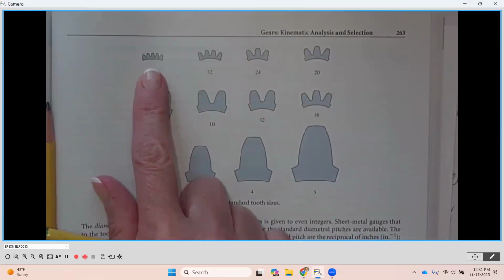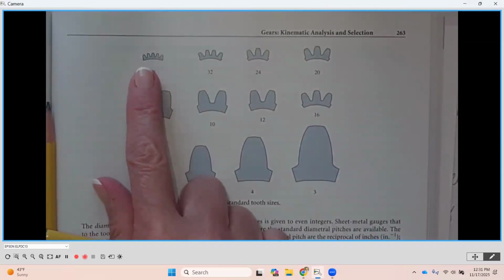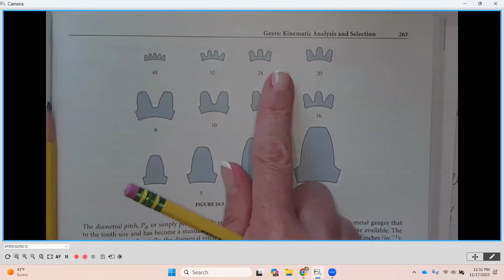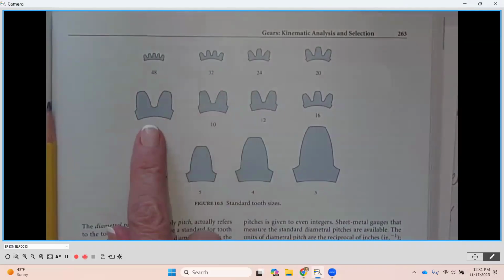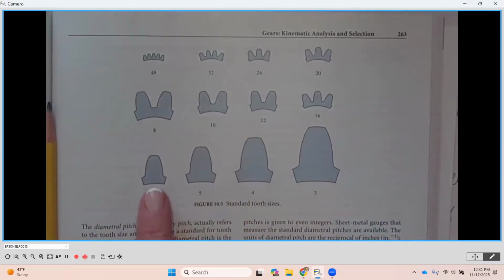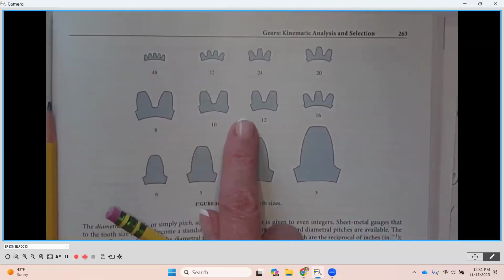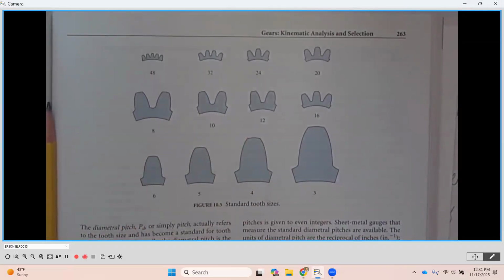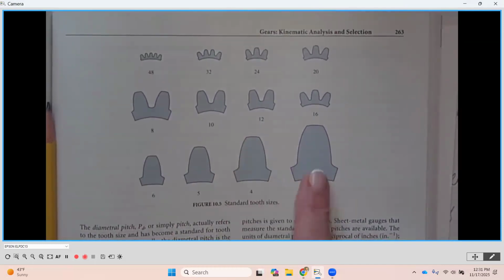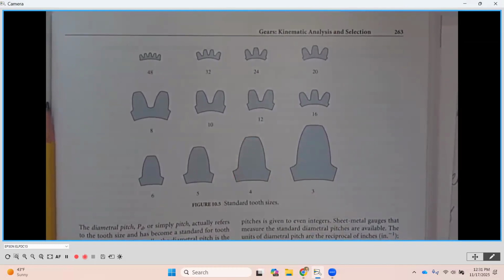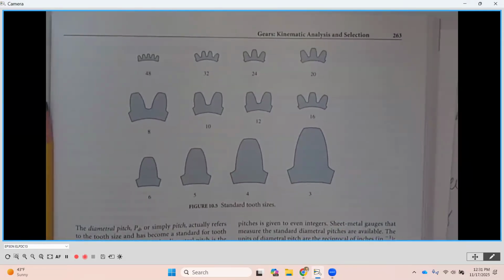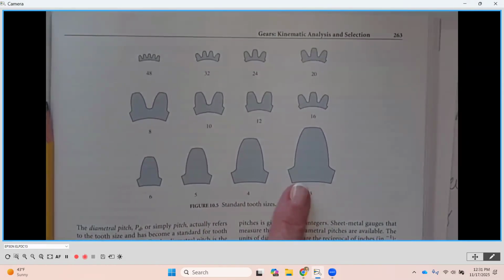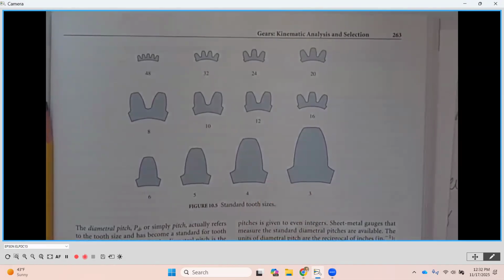Now, although these probably aren't as small, you can consider these like printer gears, you know, like inkjet printer gears to pull paper through, which are going to be smaller gears like this. Middle of the road applications, like 5s, 6s, 8s, 10s, 12s, these guys right here, are going to be machinery applications. And then these larger ones are going to be machine tools. Okay. So applications where we're going to see bigger forces, a more volatile type of environment, would be the bigger teeth. Okay.